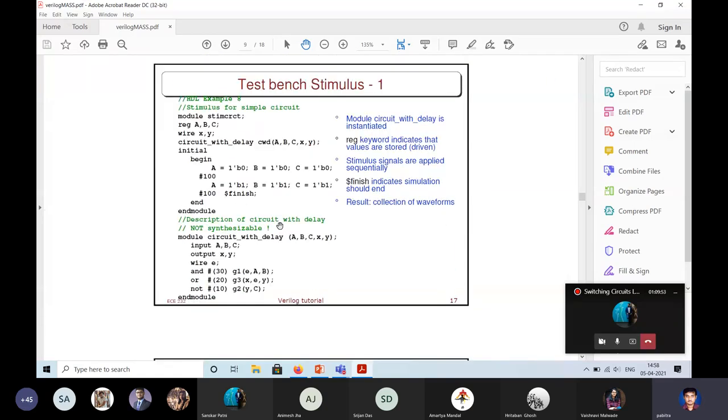All right, another important thing is called a test bench. This is the set of input values, or stimulus, that you give to simulate the circuit. We name the module like this. Naturally, this is kind of a void module, which means it has no inputs or outputs. The test bench is an input data kind of thing. You also write it as a module, but a void module with no port list, no net list.